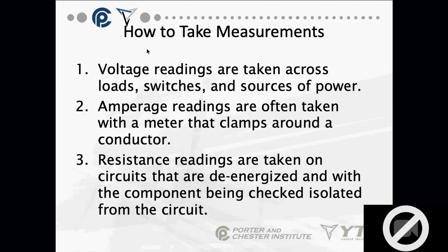When you're with your meters, and when you get into shop, first of all, if you have never taken voltage readings before, I expect you to ask the shop instructor to demonstrate this to you, or work with somebody who's been there for a few turns, because you don't just stick a meter in a socket without knowing a little bit what you're doing. Voltage readings are taken across loads, switches, and sources of power. Amperage readings are taken with a meter that clamps around a conductor.